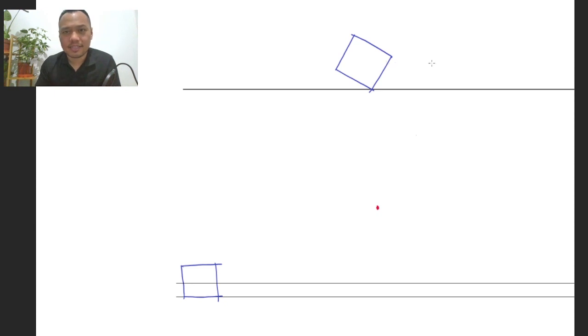Next, we're going to need to create the vanishing points. This is what makes a two-point perspective drawing. Typically, like I said, we have one face here that's 30 degrees clockwise from the picture plane. Regardless of at what angle this line right here is, we're still going to go from this side 60 degrees counterclockwise.